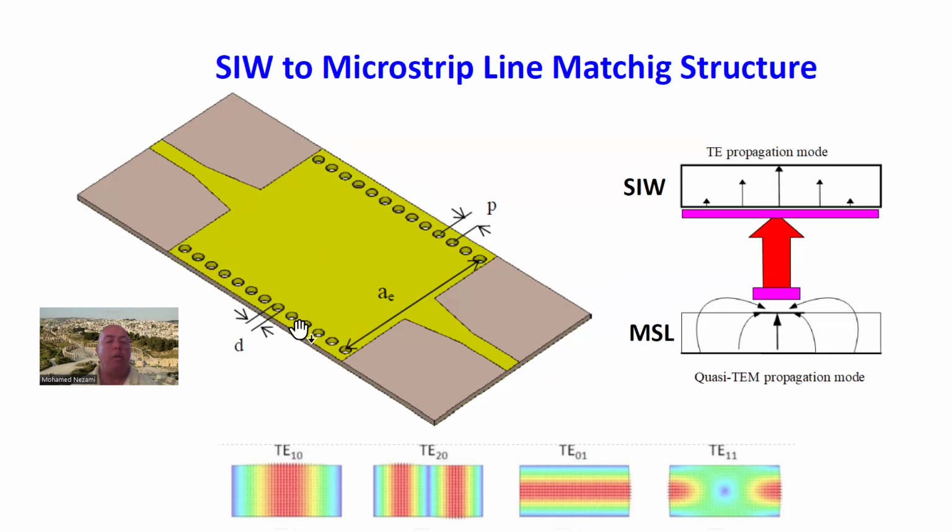The only trick is that we choose the pitch here in such a way that the electrical field would not leak out, meaning that at the operating frequency that we're at, this will look like a short. We have a cutoff frequency below which none of the electrical field of the signal that propagates this way would leak on the sides, and we would have minimum loss.